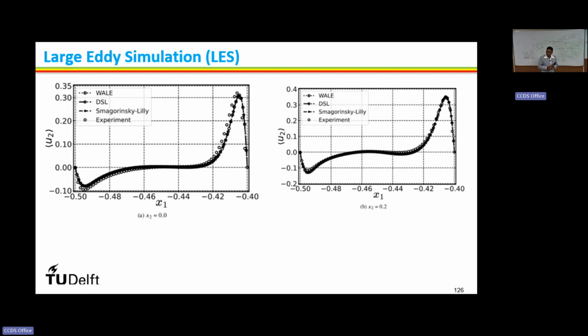Similarly, second order bounded time discretization is used for LES simulation. At least it is second order or higher, right? A bounded second order scheme is used for discretization of space, and a bounded second order implicit scheme is used for time marching. Then only are our results accurate, right?